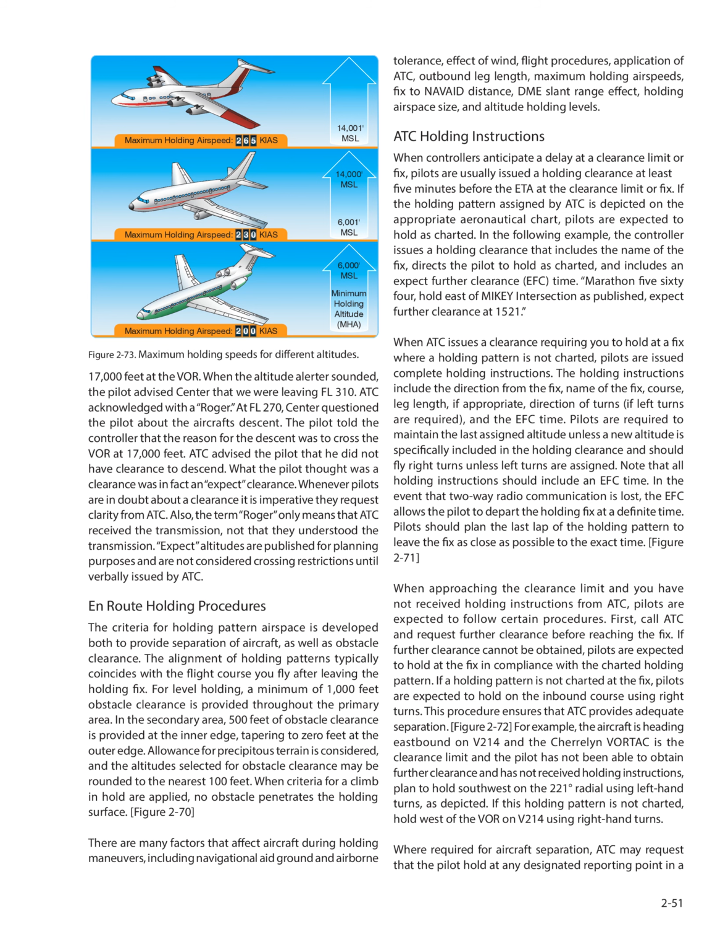When ATC issues a clearance requiring you to hold at a fix where a holding pattern is not charted, pilots are issued complete holding instructions. The holding instructions include the direction from the fix, name of the fix, course, leg length, if appropriate, direction of turns, if left turns are required, and the EFC time. Pilots are required to maintain the last assigned altitude unless a new altitude is specifically included in the holding clearance, and should fly right turns unless left turns are assigned. Note that all holding instructions should include an EFC time.